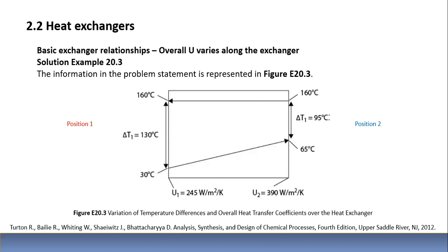Y ya no pasaba más y se perdía esa área de transferencia. Ese es el fouling, digamos. Es un ensuciamiento. ¿Por qué es ensuciamiento? Porque el café se iba secando en el interior del tubo y esa película de café seco hacía que caiga el coeficiente de transferencia de calor y se volvía el evaporador más ineficiente.